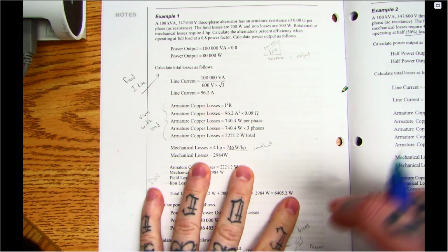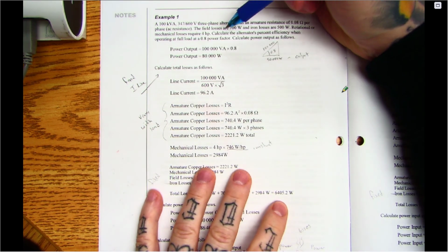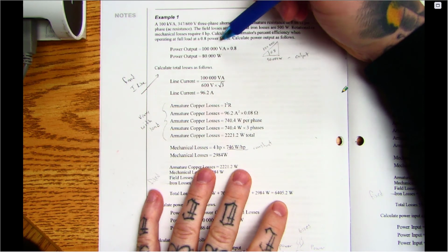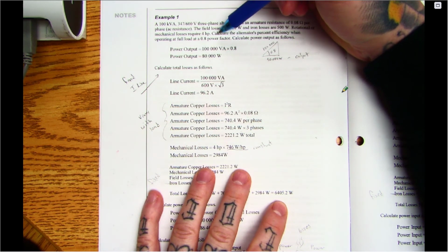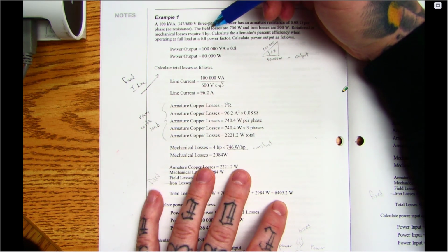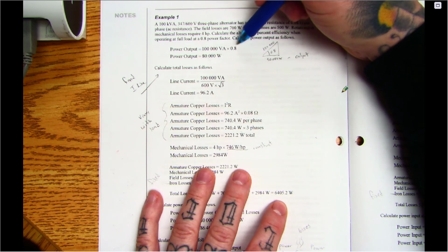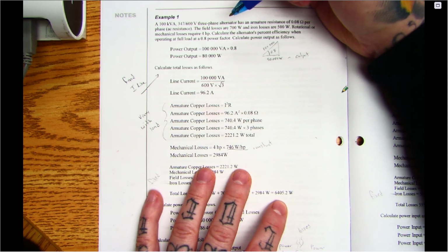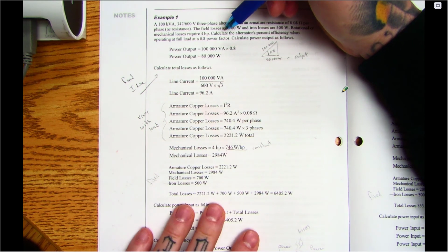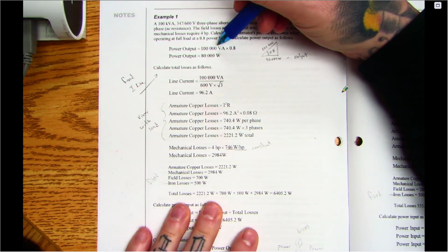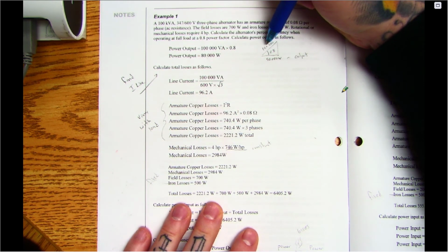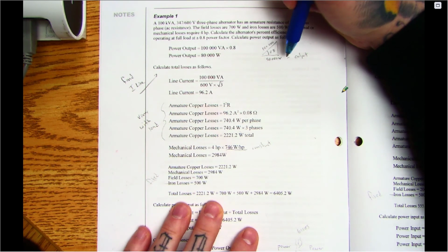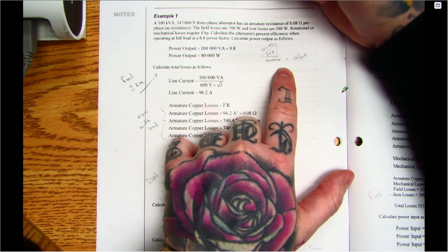So some things to just hit on here. The output is going to be based on our calculation off our rated output here. So we're basically saying we want to know the efficiency at this rated load, and power factor of 0.8. So I guess it is an actual hooked up load, but drawing rated current. I just make a little power triangle to remind me that with the VA here, I can just use power factor to find the watts. Those are output watts, okay?